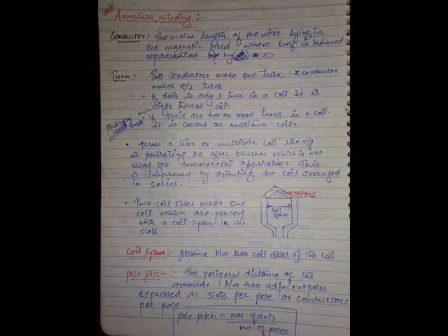One positive cycle is always 180 degrees, one negative cycle always 180. One electrical cycle means automatically 360 electrical degrees. So, if there are two poles, one complete rotation of 360 mechanical is equal to 360 degrees electrical.